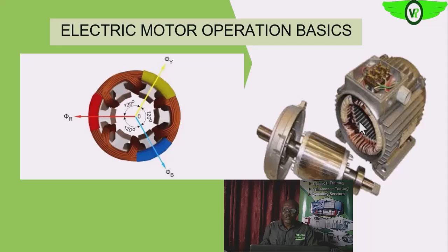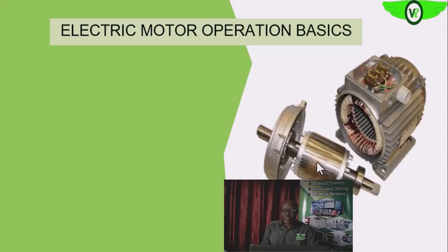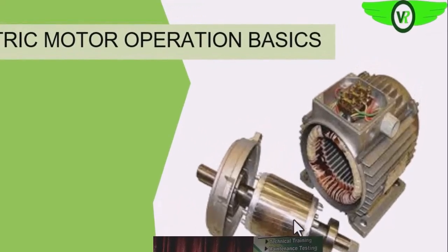Are we getting it? So that magnetic field is changing, because the terminal is directly connected to your line. As that magnetic field changes, since the rotor is coupled inside, it will induce current. That is, current will start to flow in these conducting bars. Remember that current-carrying conductors have magnetic fields generated around them, which means a magnetic field will be generated around this rotor.